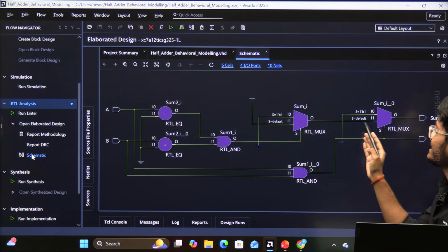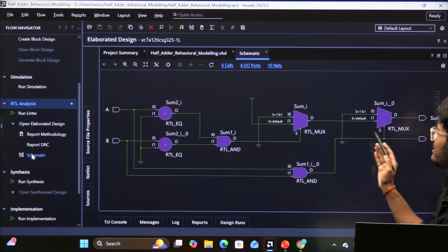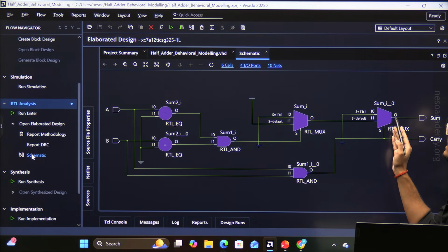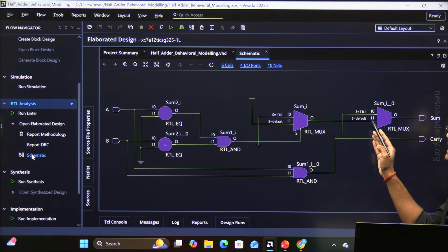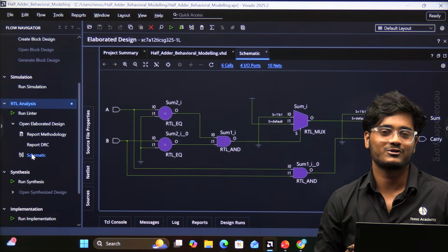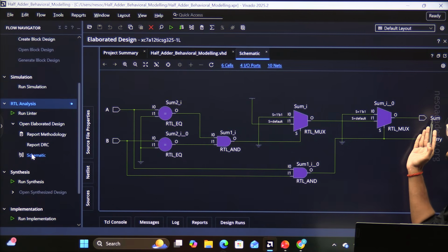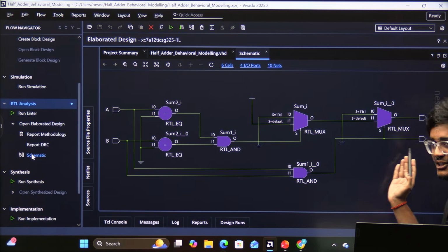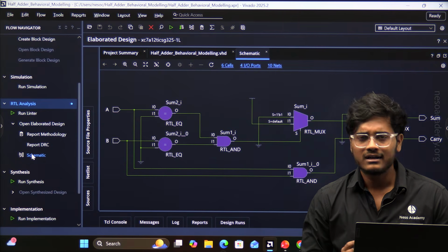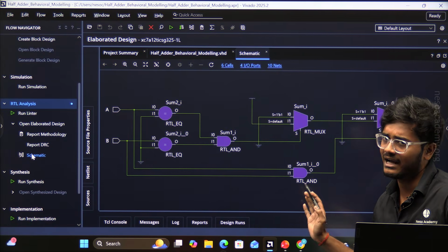And this output is directly connected to the input I1 of the second multiplexer. And I hope you remember that here select line S is equal to 0, which means input I1 will be connected to the output sum. And here input I1 is equal to 1, which means sum will be 1. So when A is equal to 0 and B is equal to 1, then we are getting sum as 1 and carry as 0, which is correct. And I hope you understand this schematic diagram. Similarly, you can verify the remaining two combinations as well using the same schematic.